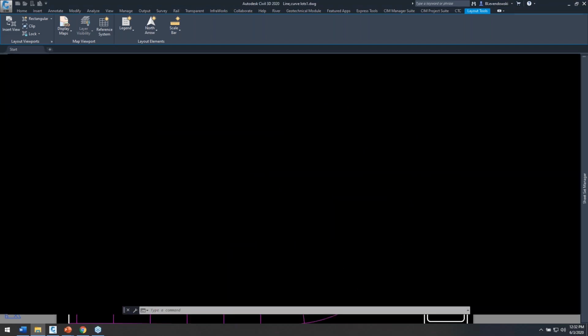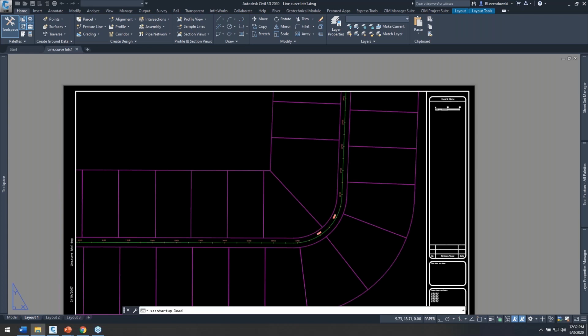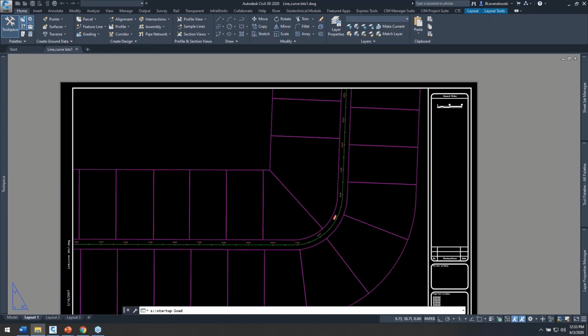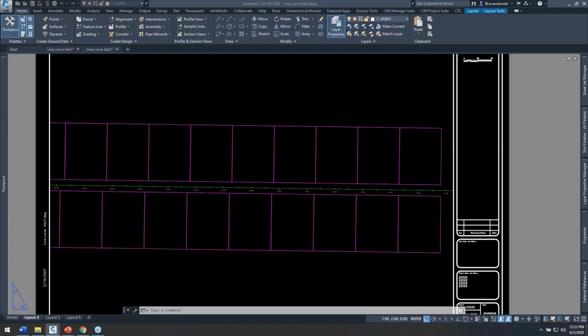And this is where we've got line and curve labels to apply to a whole subdivision, right? And this is quite literally thousands of labels where we want to call out bearings and distances on all of our lots, on all of our common areas, perhaps along right-of-ways, okay? And so let me show you how this works. And this is a Civil 3D label object now, right? So all the properties that are in those label styles, that just comes from the label style itself.